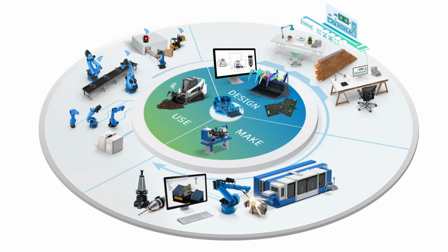So what we've looked at today, we've gone through the design aspects, so having the ability to go ahead and do T-spline modeling, so some very free-form shapes, moving that into parametrics, having the ability to quickly and easily start to cut material using standard line art sketches, having the ability to offset parts very quickly within Fusion, then also create all of those mechanical links.